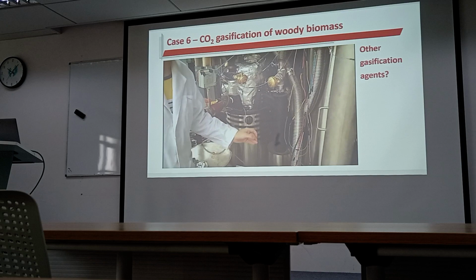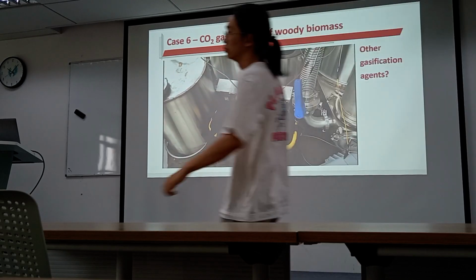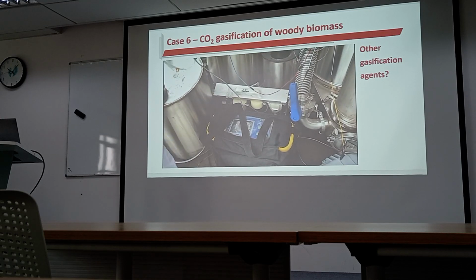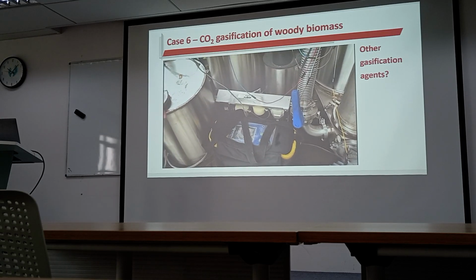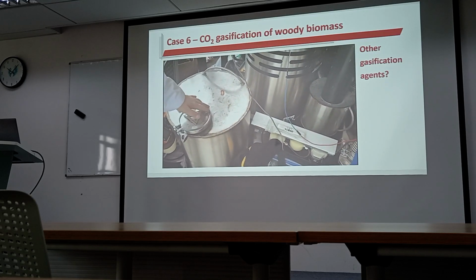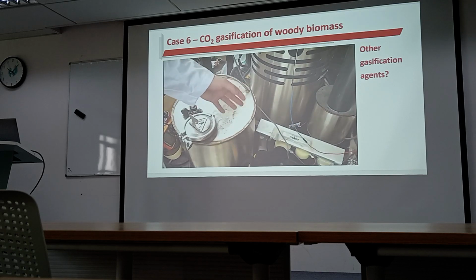And the syngas is also measured in this gas analyzer to know its chemical composition, regarding what the gas composition of CO, CO2, H2 is in the produced gas. And here, the biochar produced is stored in this char tank. And when the experiment finishes and it has cooled down, we will collect it.